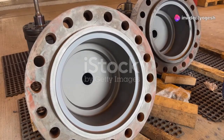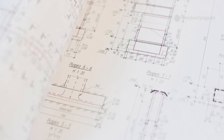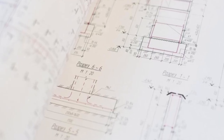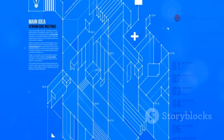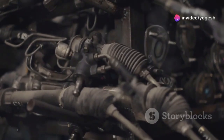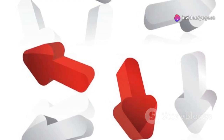Let's put this into practice with a flanged bushing. It has a central bore, keyway, and staggered bolt holes. Hidden lines would be a nightmare, so we use an offset section. The cutting plane zigzags to capture all features. Draw the cutting plane line in the top view, labeled AA. Arrows point down, replacing the standard front view.